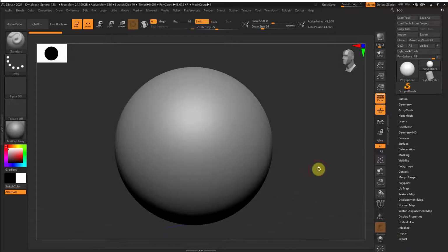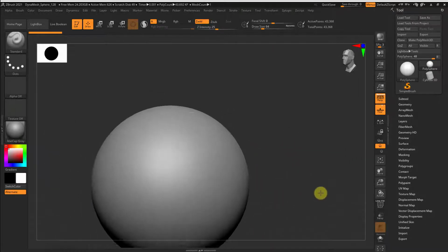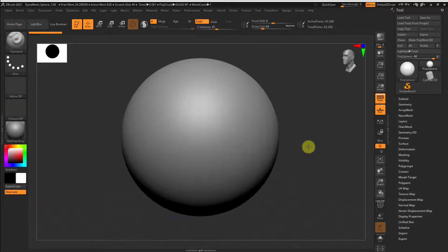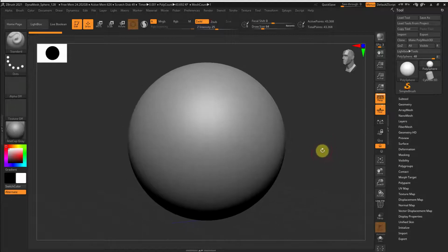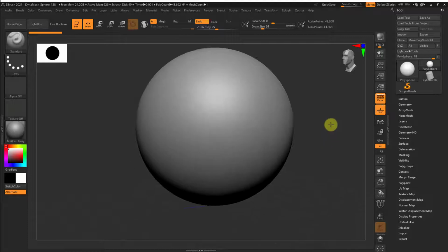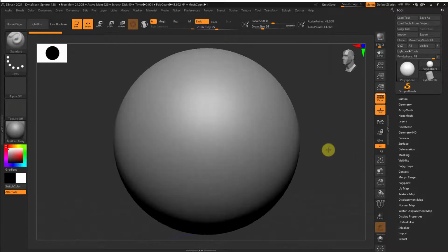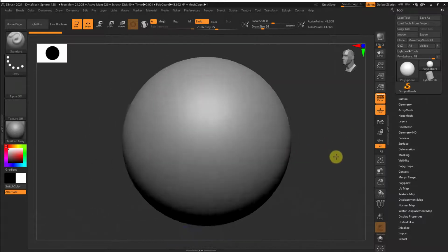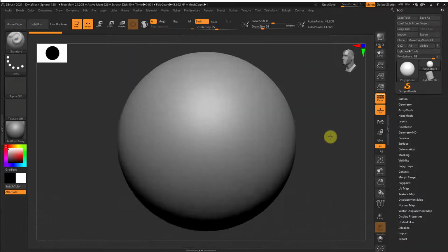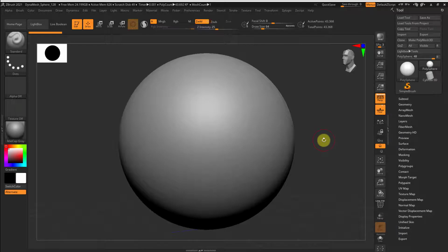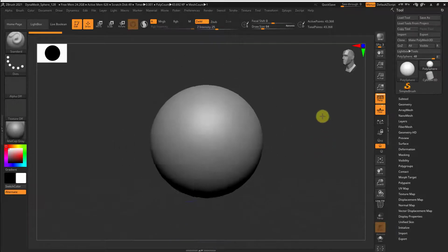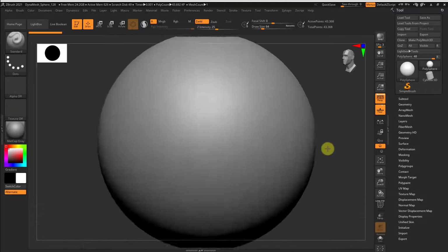So that's how you rotate. I can hold Alt and click and drag outside of the mesh to pan around. I can zoom by holding Alt and clicking as if I were to pan, but once I'm clicking and moving around, I can let go of Alt and then move the mouse or the stylus up and down, right? So again, that's hold Alt, press down with the stylus, let go of Alt, and then drag up and down to zoom in and out.